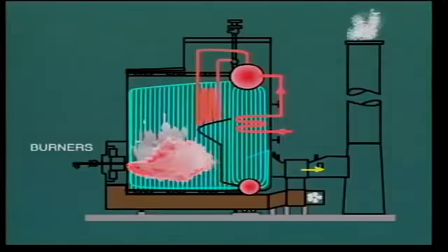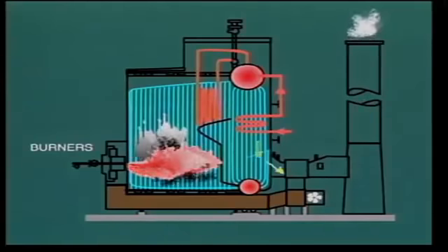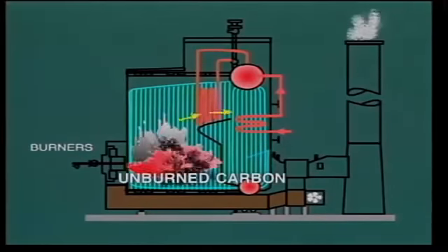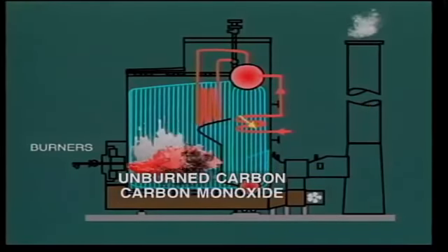Indeed, if we were to provide only the theoretical quantity of air as shown by calculation, we would probably end up with incomplete combustion in the form of some solid carbon particles, that is, unburned carbon, and some portion of carbon monoxide instead of carbon dioxide.